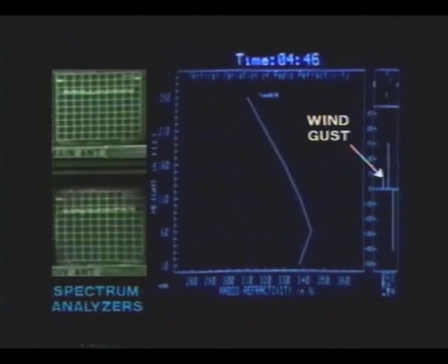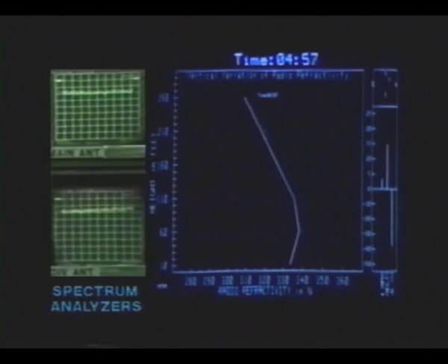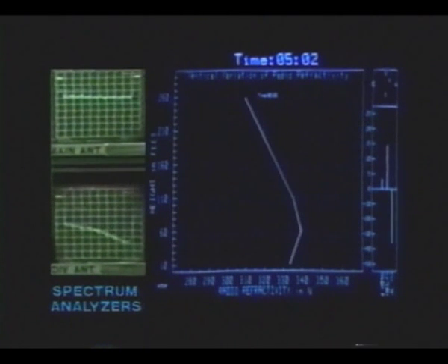for over an hour. Flat fading occurs when the main beam is bent downward by the negative refractivity gradient, allowing reflected signals to approach the magnitude of the main beam and cause significant in-band notches, a condition clearly seen in the following segments. Waves form on the interfaces of atmospheric layers much the same way waves form on the surface of a lake. These surfaces cause the magnitude of the reflected signals to fluctuate rapidly, as seen in the following segments.